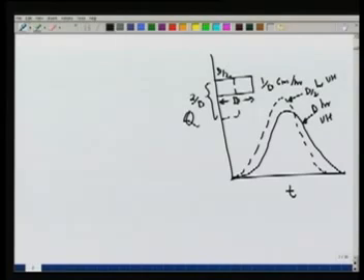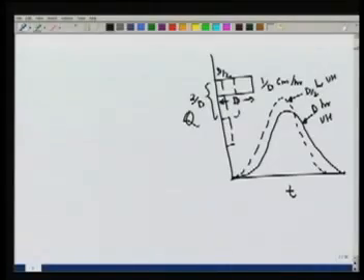The same argument can be extended further. If we further reduce the duration by half and increase the intensity to twice, we would get an ERH which is very narrow and the intensity is very large. In that case, the UH ordinate peak will again be larger, the time base will become smaller, so we may get a curve which has a smaller time base but a higher peak.